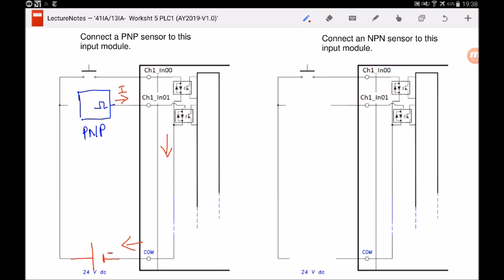And the positive terminal will be this way. So this is how you connect the battery polarity. Next, the positive terminal of the power supply will be connected to the positive terminal of the sensor, and the negative terminal of the sensor will be connected to the negative of the power supply. You can choose to draw dotted lines or solid lines, since there's nothing below this sensor.